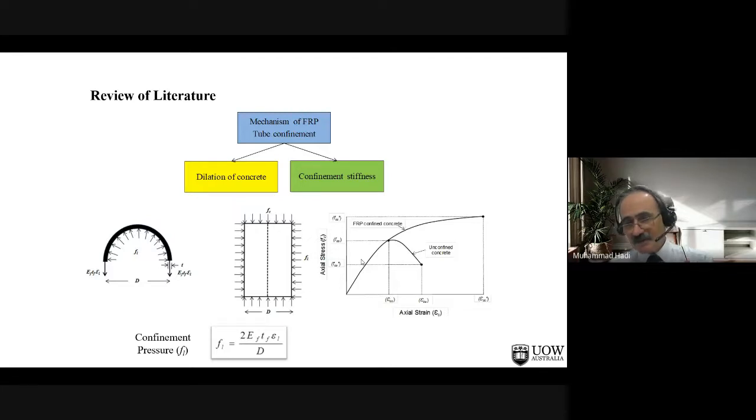If you take sigma Fy equal to 0 and you sum, you will see that the confinement stress in the tube will be applied on the concrete. Of course, this is based on Poisson's effect.